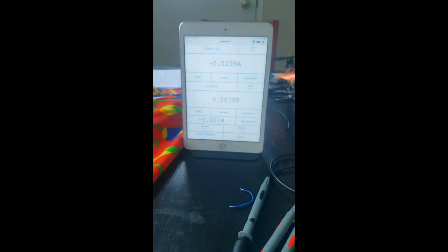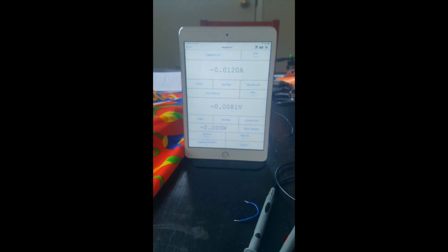let's bring the solar cell in perpendicularly, and if it's four strings of four, that top left part of the column is essentially one combined parallel generator. So it should be able to put out its own current, but we get less than a milliamp. We get no current. So it's more than likely that this is two strings of eight, because shading only half of it still allows it to push out more or less half the amount of current.